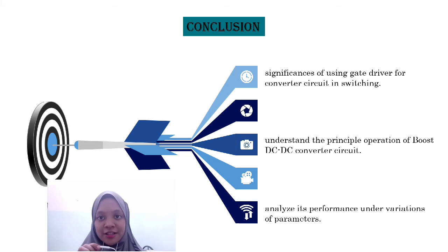In conclusion, we could explain the significance of using the gate driver for converter circuits and understand the principal operation of the boost DC-DC converter circuit. We also could analyze the boost DC-DC converter performance under variations of the parameters. The simulation done in MATLAB software also brought more understanding of the circuit's waveforms, but we have to verify that the value from the simulation was similar to the calculation value. In the calculation section, we can see that both results are the same. Besides, the calculation is more accurate because the simulation value was simplified.